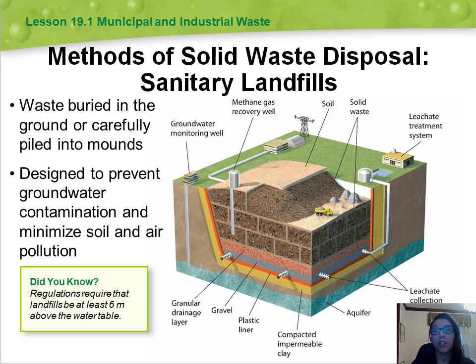So as you can see in the picture, we have something that's called a sanitary landfill. In modern sanitary landfills, waste is buried in the ground or piled up in large, carefully engineered mounds. In contrast to open dumps, sanitary landfills are designed to prevent contamination of groundwater and to reduce soil and air pollution. Most municipal landfills in the United States are regulated locally or by the state, but they must meet national standards that are set by the EPA.